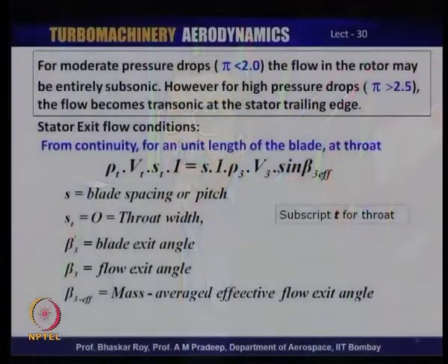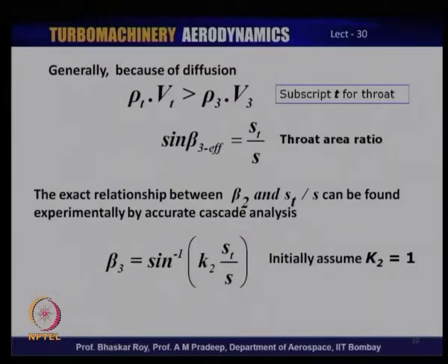So, these are the places where, when you get into CFD, more and more CFD would have to be used to get these features refined, and super refined if necessary, to get those things done correctly. Now, let us take a look at some of the other things that we need to get into. There is a possibility that some amount of small diffusion may occur from the throat, either of the rotor or of the stator, in which case some amount of diffusion does occur, and hence there is a change of density and velocity which may happen during the process of this mild diffusion zone.